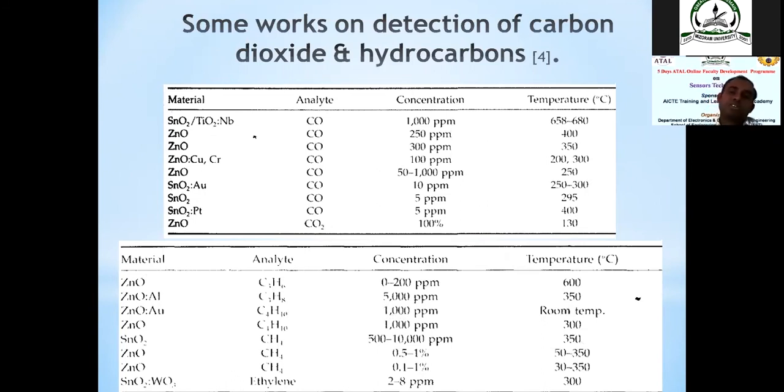If we are going to use a MOS sensor for combustible gases, and its temperature is more than room temperature, it is possible there is a combustion, and it may cause a disaster in different industry applications, because there we want to detect the gas. We don't want to inflame all those gases. So in those cases, the temperature is a very important factor.